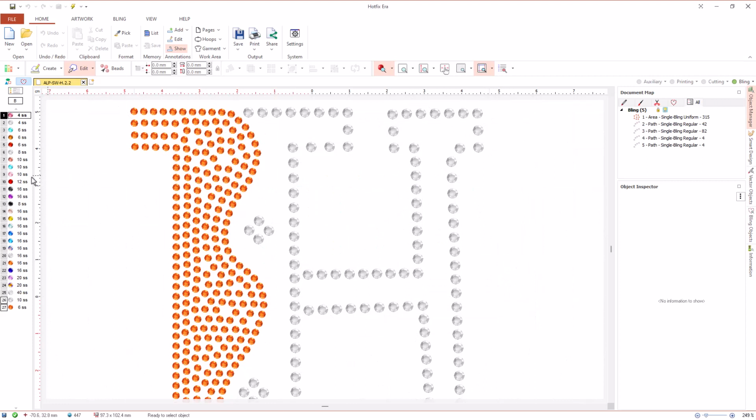We can also add and manipulate guidelines graphically. By placing the mouse over the ruler, holding down the Control key and dragging, we create a guideline. We can move it by dragging this symbol, and using the context menu, right-click, we can change the color and delete them. Within the show functions we find controls that allow us to show and hide certain elements of our objects. In complex designs, it is often useful to hide beads, object outlines, or other elements.